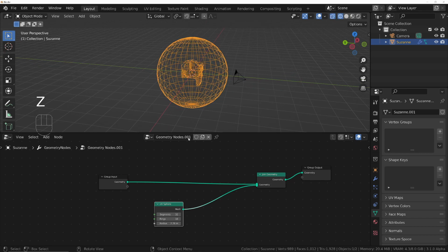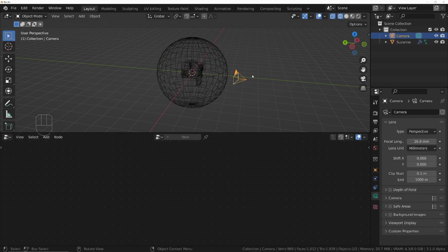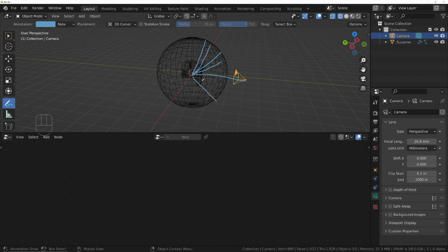So go into wireframe mode. I just want to delete the back half of the sphere. And to do that, we can use the vector. And a vector is basically a line between the origin and the object, and also between the origin and each point of the object that we want to delete from. And we compare these lines, and if they're pointed in the same direction, we want to keep them. If they're pointed in the opposite direction from the camera on the sphere, then I want to remove them.